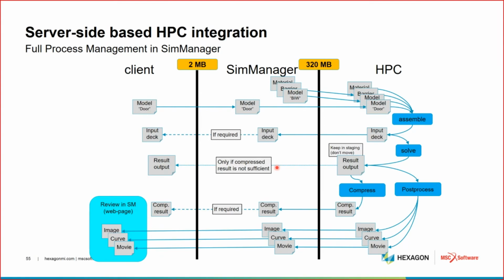In the example I showed earlier, I was running Patran in batch. In that instance, if I ran Sol 101, I generated images and individual values. I've got some PCL scripts to go through that whole process. When I ran Sol 103, I generated some movies automatically. And whenever I ran Sol 109, I didn't run Patran at all. In that case, I executed some Python scripts to strip through an F06 file and generate curves out of the dynamic response at specific nodes within that solution sequence.